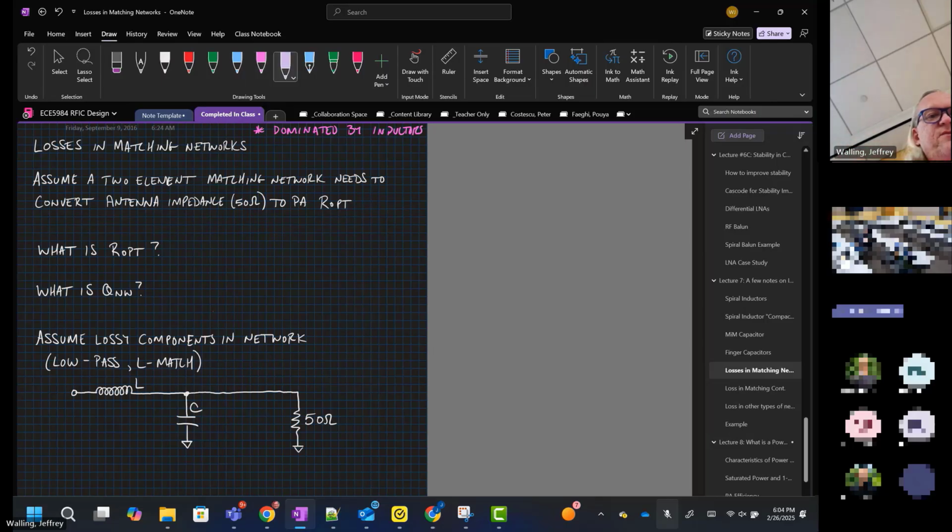In the process that we're using, if you cascode transistors, you might be able to use a supply voltage equal to 2 volts. Supply voltages in CMOS tend to be labeled VDD for the drain supply. I tend to forget I do have some folks that are not pure circuits nerds like myself. So VDD is the drain supply voltage. Let's say we want an output power equal to 1 watt, and we want to operate in a Class A mode. Class A is the mode for amplification that most of us think of. It means we put a sine wave in, and the transistor conducts for a full sine wave at the output.